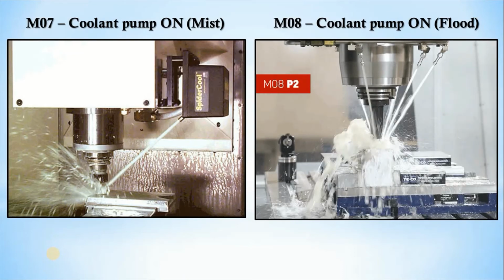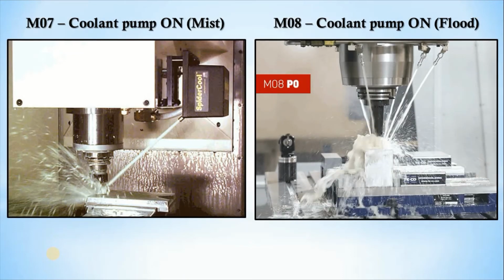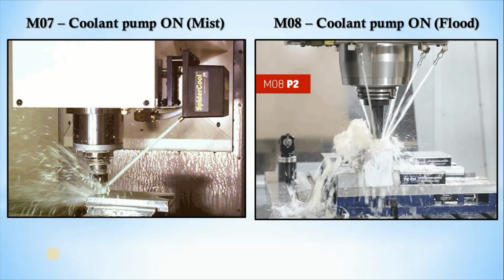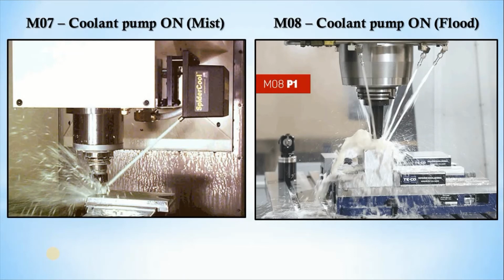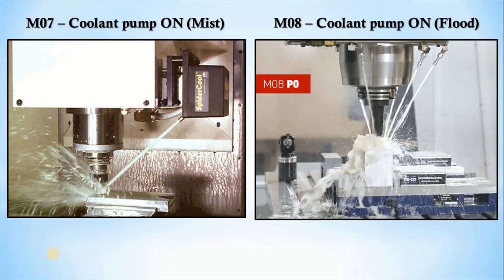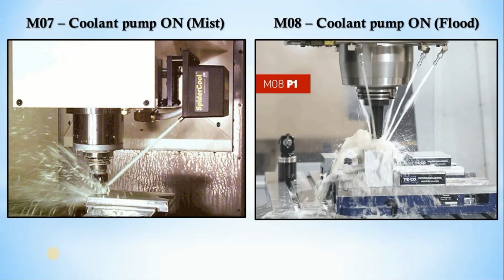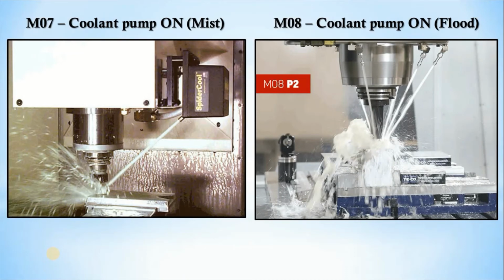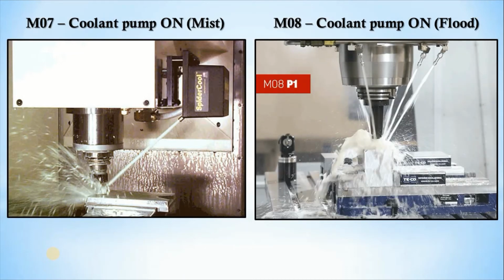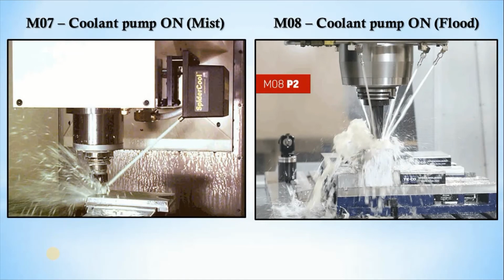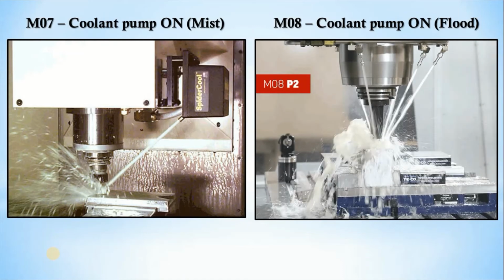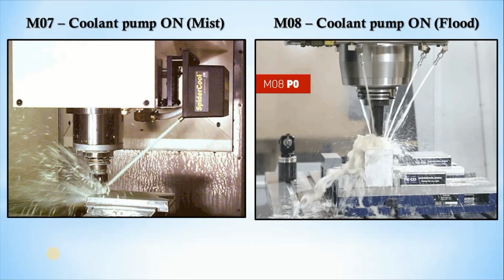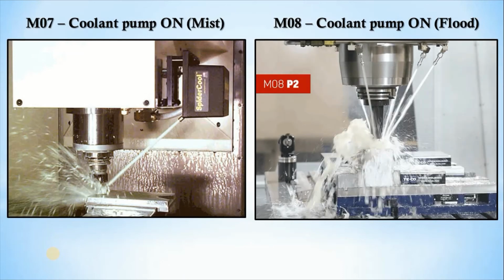If we are using these types of machining conditions, there is a possibility that a large force will appear, and due to that large force there will be heat generation at the contact point of the workpiece and tool. So due to this heat generation, there is a possibility that tool wear will occur in no time. Also, that will affect the surface of the workpiece.